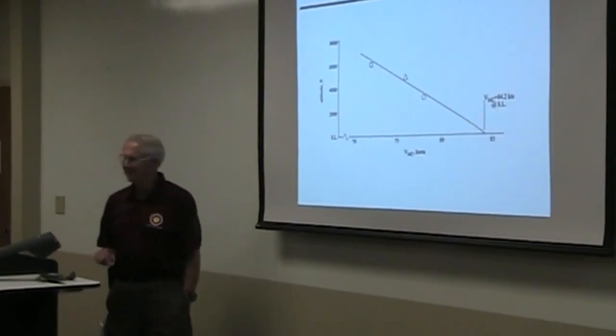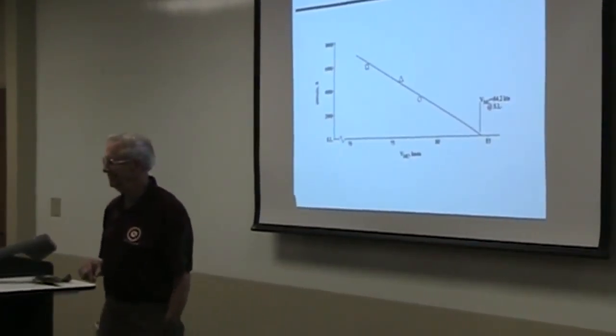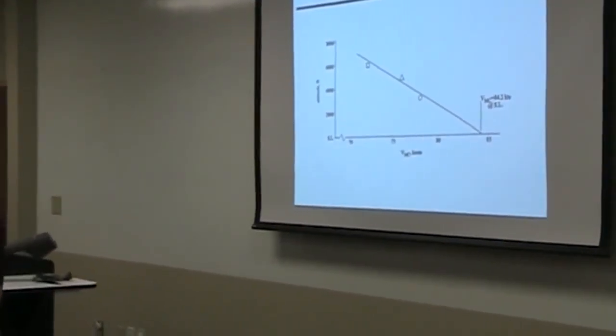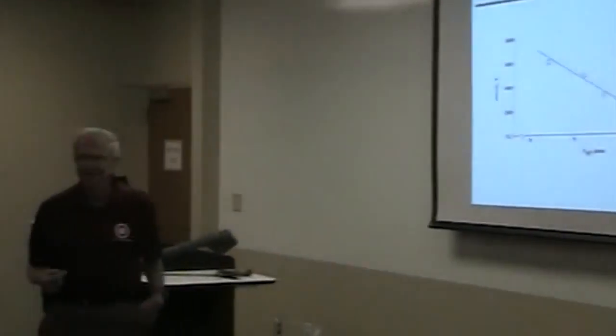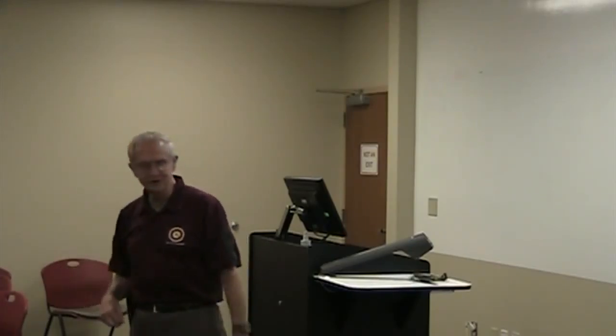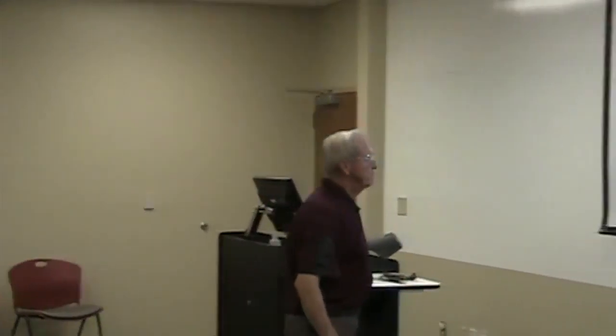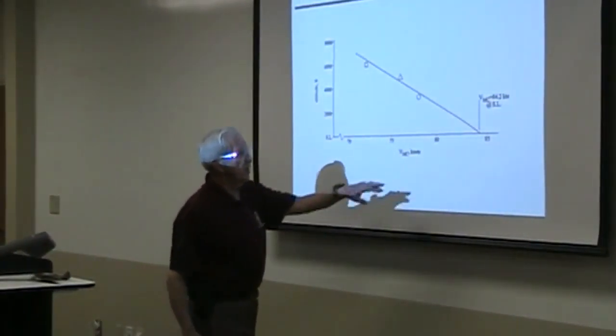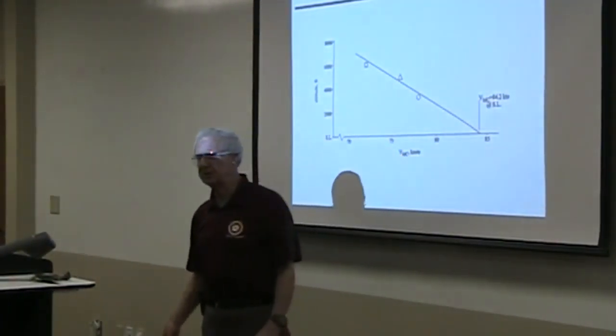That way we don't have to test at sea level. Okay, we're getting around that point. Now, this is a dynamic maneuver as a rule, because the engine fails, it doesn't give you a chance to get all set up. When the engine fails, it fails. And you have to respond. Well, so this gives you what we might call a static VMC.